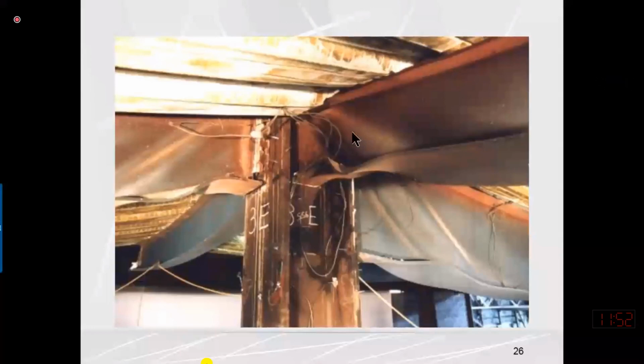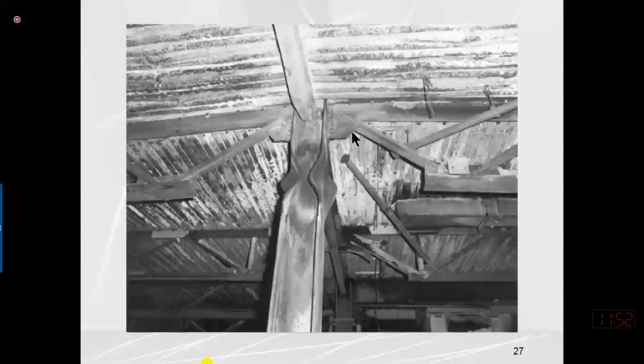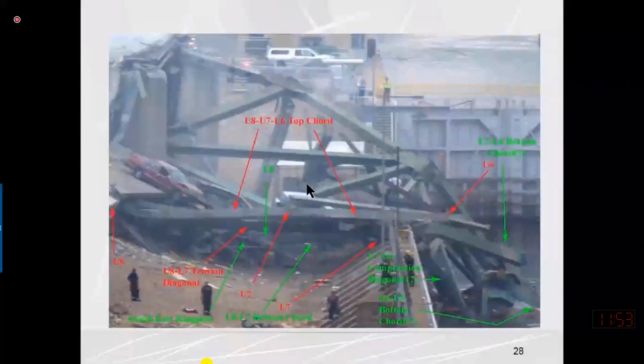So here in this diagram, this is the column. This is perfectly straight. It means it is stable against overall buckling. Why stable against overall buckling? Because it didn't bend in the left direction. But local flange buckling is there. Local means the flange buckles only at a small portion. Again, what is the reason? Because bf over 2tf value, or b over t ratio, of this projected leg of the flange is larger. And in this other example, overall buckling in the column occurs and the failure occurs due to overall buckling.